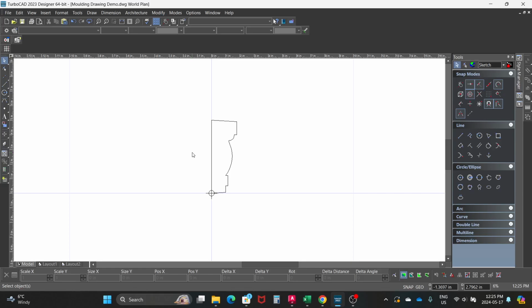I'm just going to go over the process on how I would start with a profile that's finished dimensions, draw a template for it for the coating machine, and then draw the foam that I would cut out with the right offsets from the template so you get the right coating thickness. So basically, everything you need to know to start with a profile, draw the templates, and draw some pieces to cut out. So let's get into it here.